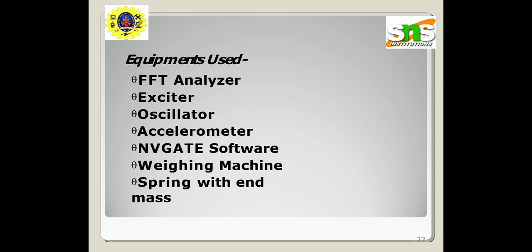The natural frequency of the tuned mass damper is basically defined by its spring constant and the damper ratio determined by the dashpot. The tuned parameter of the tuned mass damper enables the auxiliary mass to oscillate with a phase shift with respect to the motion of the structure. In a typical configuration, an auxiliary mass hung below the nacelle of a wind turbine is supported by dampers or friction plates. So, dampers in buildings and related structures are huge concrete blocks or steel bodies mounted in skyscrapers or other structures.